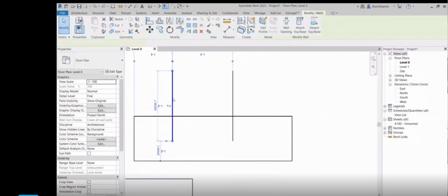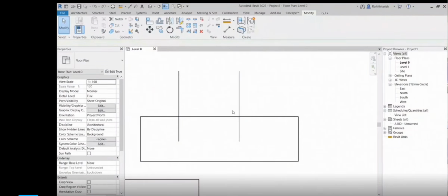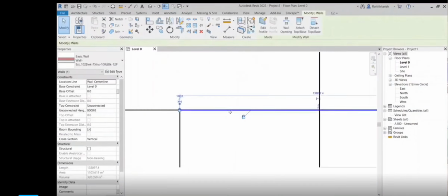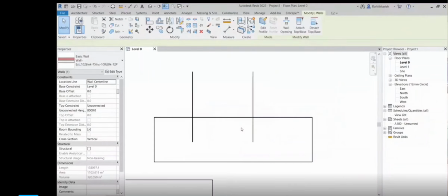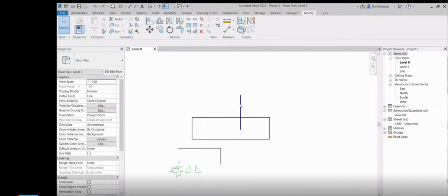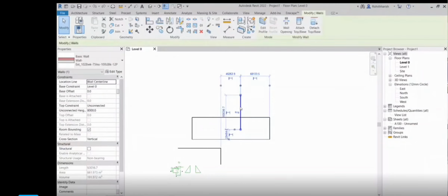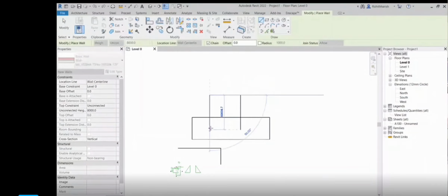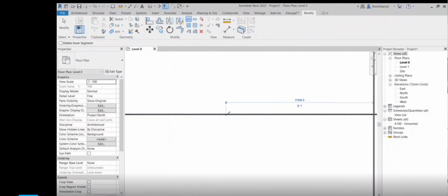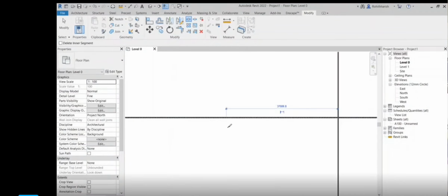Just a second. I'll go here, select the split element like this. Now you can see that this is different and this is different. Now if I go to trim this and this, you can see this portion will be trimmed. I want to do the same thing here as well, like this. This is how we'll be creating two separate splits.